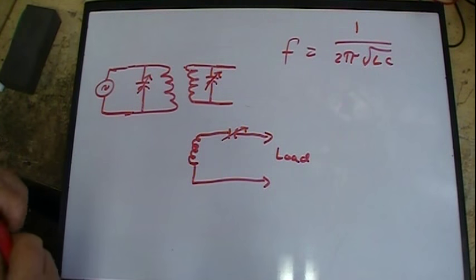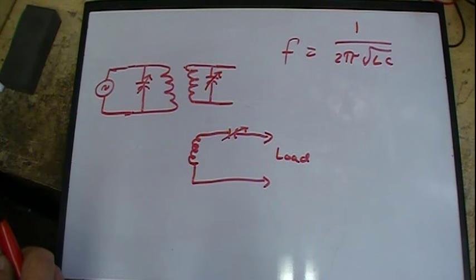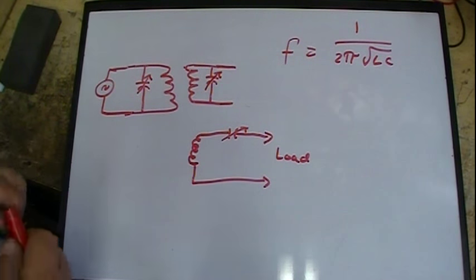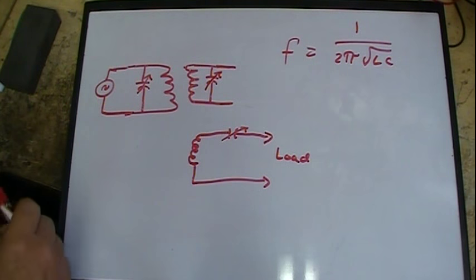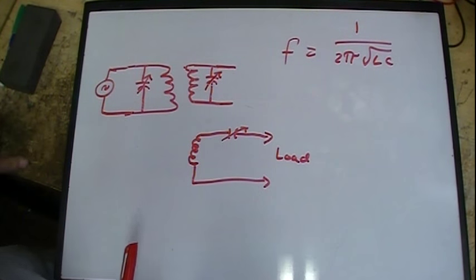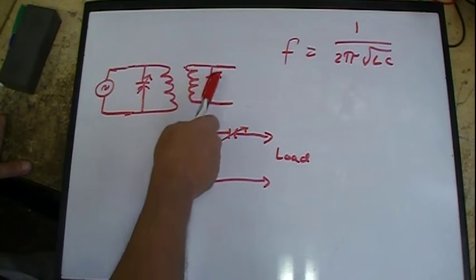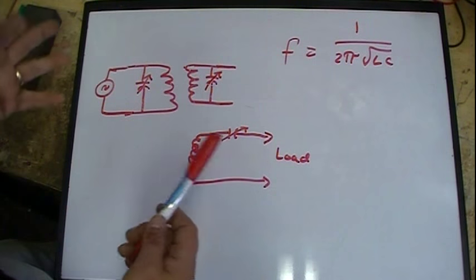You measure DC resistance, but generally they have the same number of windings using the same size wire, so the DC resistance will be pretty darn close, exactly the same. They use the same size caps, whether they're trimmer caps. These may be trimmers, such as the older IFs, or they may be fixed, but they'll be the same size.